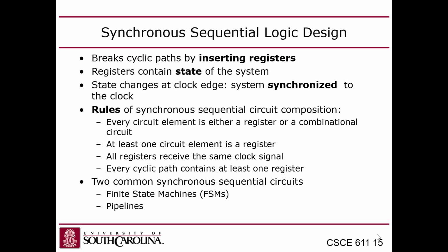Okay, so one of the common mistakes that students in this class make is they'll forget to put a delay on that stall signal. So what will happen is the stall will not affect the next instruction, it'll be affecting the current instruction. So you'll end up with a combinatorial loop where the control unit will say, oh, I got a branch, and the branch should be taken, so I'm going to have to stall.